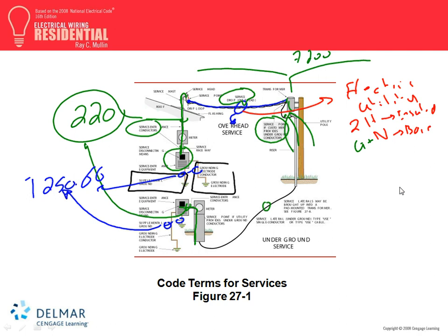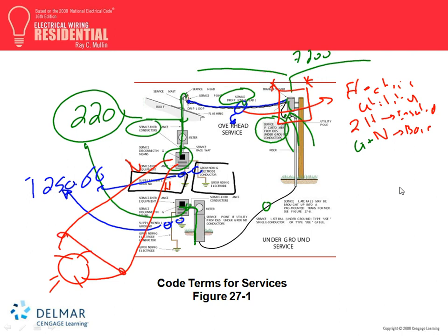One thing to remember is that a short circuit wants to go to the source of the current. What's the source of the current in these two systems? The transformer, right? The power source of the current is the transformer. So the box stops with this piece of equipment, guys. If I have a short circuit right in here, if I have a light, and my light is powered from here, and from here I have my neutral, and I have my hot, and I shorted them, the short circuit current is not going to go to Mother Earth. Where is the short circuit current going to go? To the source. Okay, so the short circuit current is coming out of here.